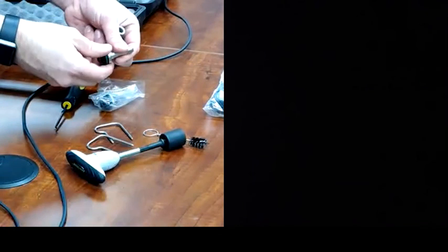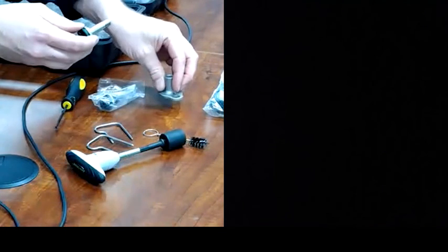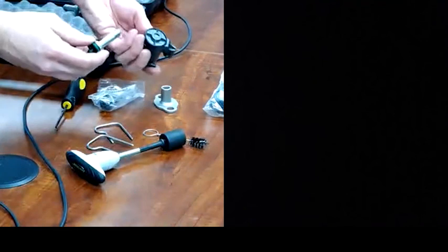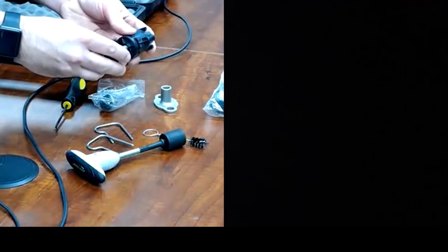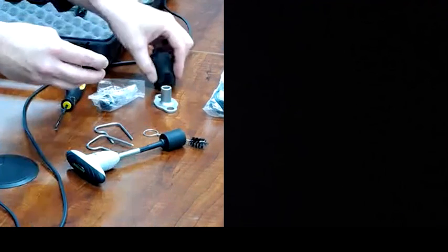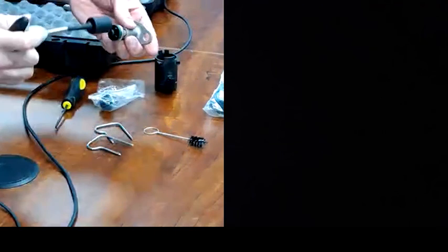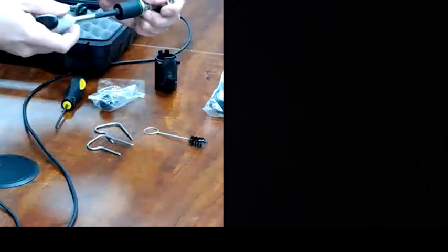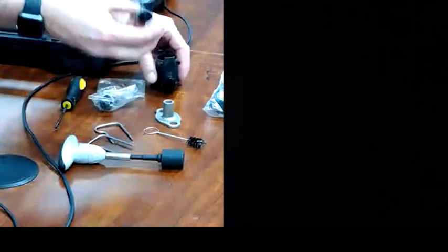Don't use, again, a vice grip or anything on the stem here. You can finger tighten them if you really need to. The other thing that's nice, again, on the bottom of the solenoid is it's actually keyed as well, so you can use that as another option for torquing these. Okay, but I go ahead, I take my 17 millimeter torque wrench, let it click, and that is now spec'd the way it should be.